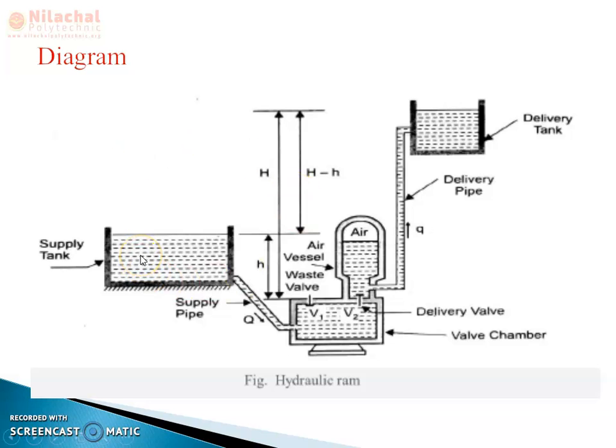First, you should know what water hammering, or inertia force of water, is. When flowing water is suddenly brought to rest, the change in momentum of the water mass causes a sudden rise in pressure. Based upon this principle, the hydraulic ram pump was developed.